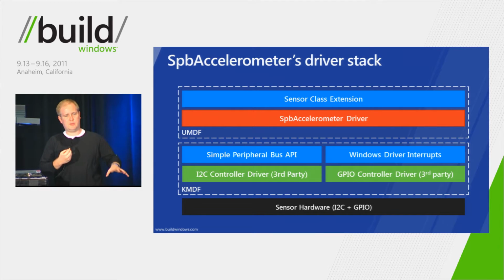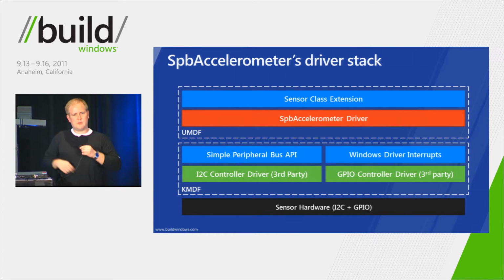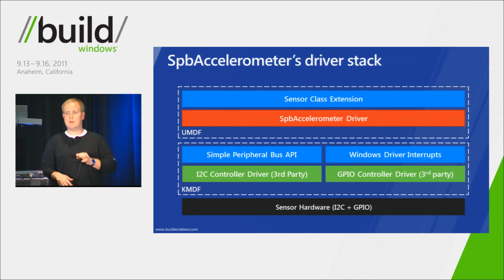we're looking at USB HID and HID over I²C as well. Those are the two. I²C, absolutely. So these devices that you see up here are all running with I²C. Oh, okay. Thank you. On many platforms, especially SOC, you don't really have a whole lot of access to USB or PCI. So these low-powered buses are great for system-on-chip platforms that really might have one USB controller, and it would be a lot of power to put in additional hubs.